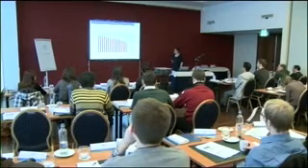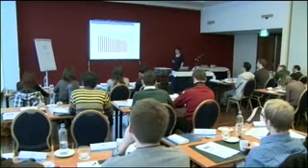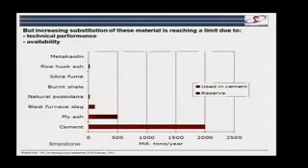Now, what are we using to substitute the clinker? Well, we're using a very wide variety of things, mainly in Europe and most other industrialized countries. The main 2 materials we're using are fly ash and blast furnace slag.